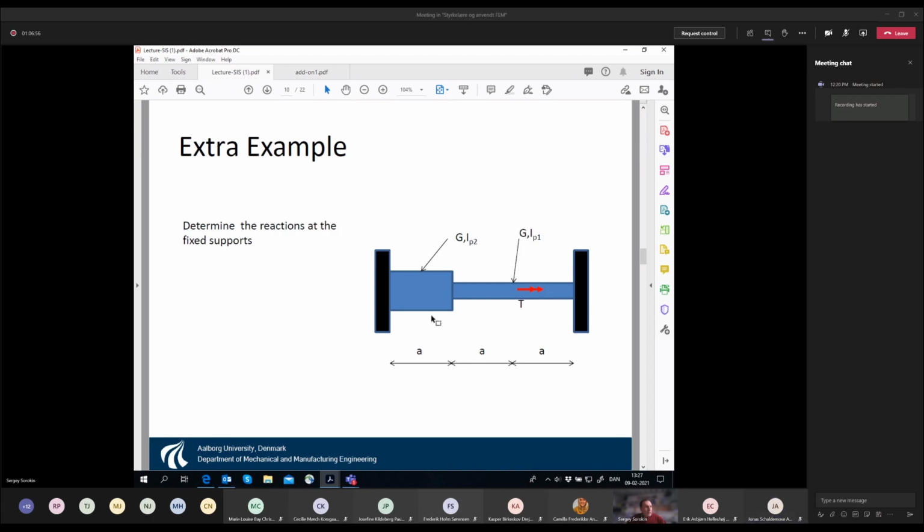So we measure the rotation angle with respect to this left edge. So at this left edge, we count the rotation angle. Since it is welded here and welded here, it may rotate in different directions, clockwise or anti-clockwise, along the length. But as we arrive at this cross-section, the relative rotation of this cross-section with respect to this cross-section must be 0.